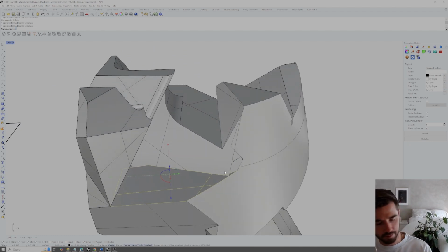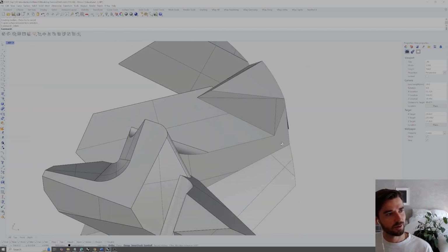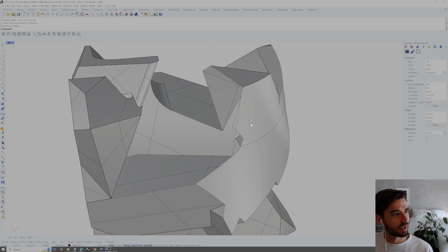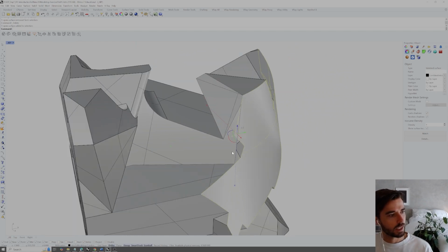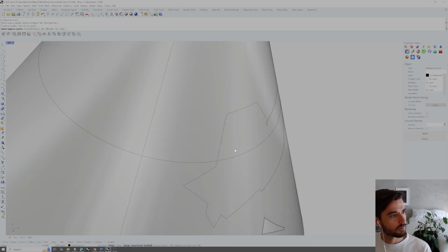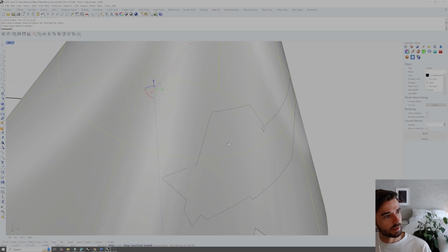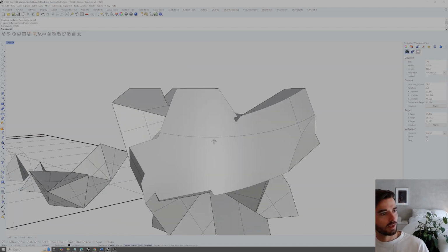We can split this bottom plane, deselect the portion that we need. So we're slowly building this out to remove that messy bit there. And now this outer edge, we just need to untrim to infill that. So if I go ahead and say untrim, now we should be able to take this cone and split each of these bordering surfaces and polysurface to just get this central profile, which we do get, and then we can delete it.